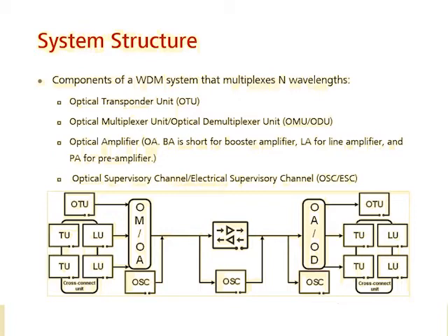And also we have another thing. You can see the last one, optical supervisory channel and electrical supervisory channel. This also tells us our WDM system supports two different supervisory channel transmissions: optical supervisory channel, or, if you don't want to use the OSC board, you can use electrical.